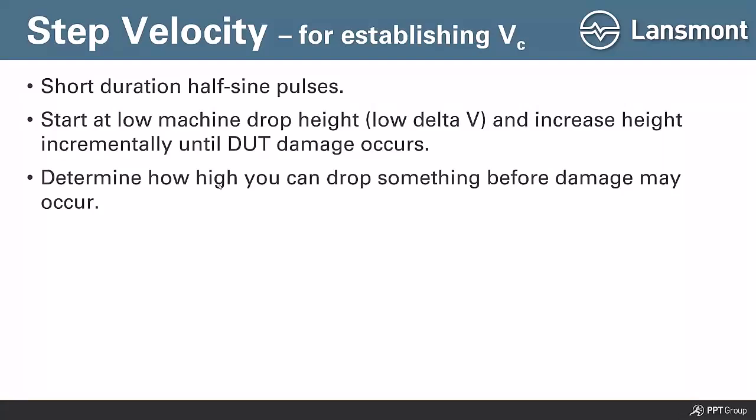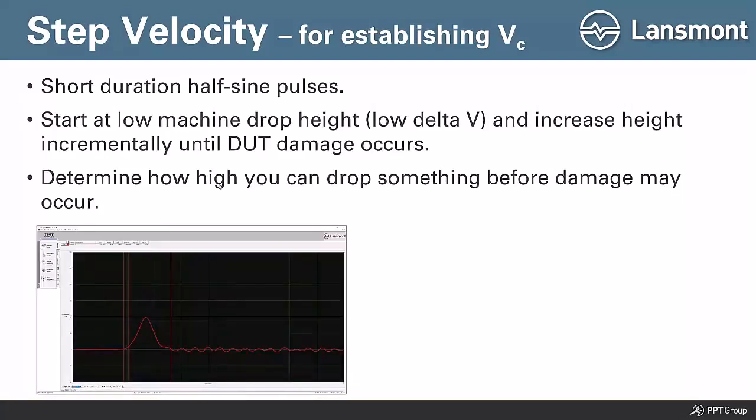By doing the step velocity testing and establishing that critical velocity change, this allows us to tell if, at the end of it, we are even going to need packaging. Even before we go on to the next step, which is the critical acceleration side of the testing, this testing alone says how high I can drop this.